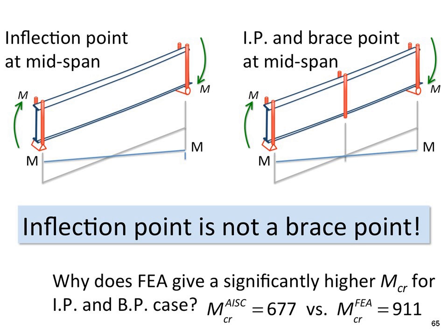All right? And so I'll let you wrestle in your mind with why the AISC only gives you 677 in that example, but the finite element gives you so much more. And I'll give you one little hint. Think about continuity.